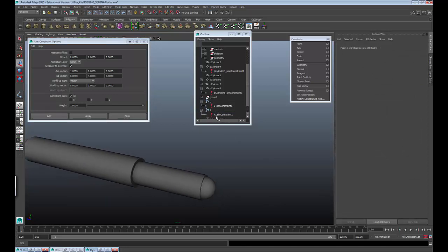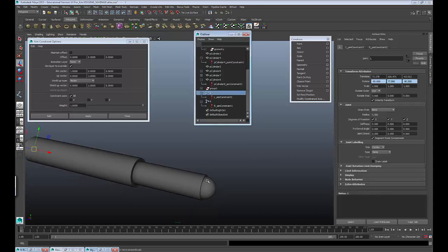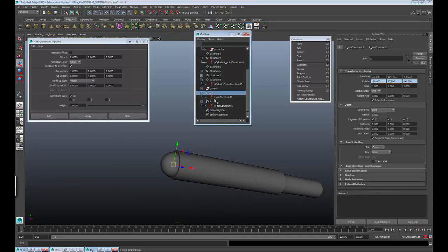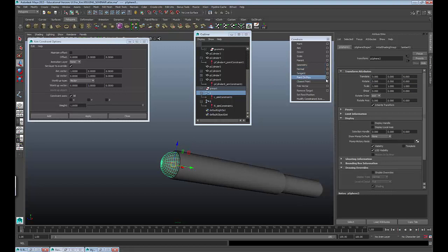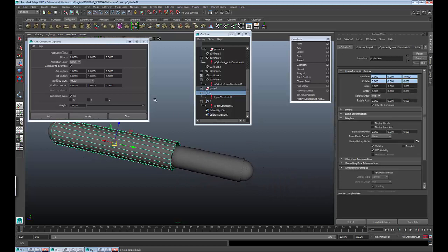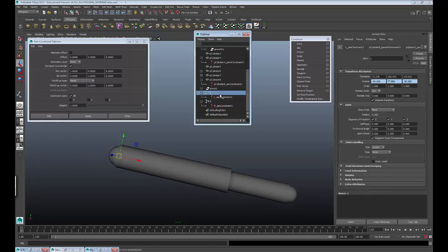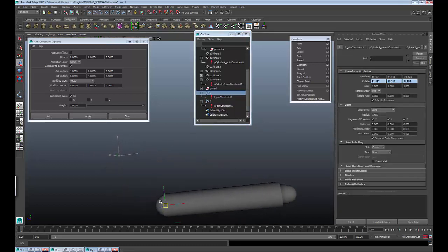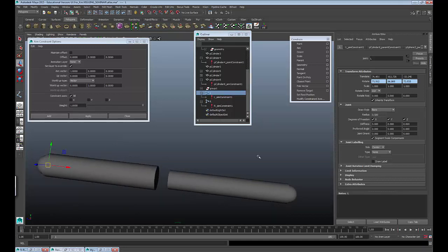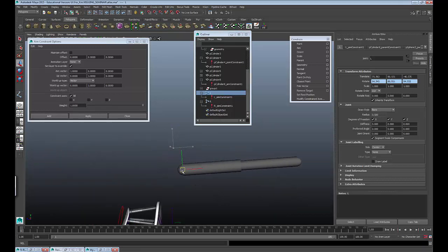And I'm just going to connect my geometry to these joints with a parent constraint. So I'm going to select my joint, select the geometry, similar to what we did yesterday, and just use the parent constraint. And then I'll just do the same for this one. So now when I move this side over here, I can keep moving it indefinitely, but as long as I move it within a certain range or a limit that we're going to set, that piston's always going to move.